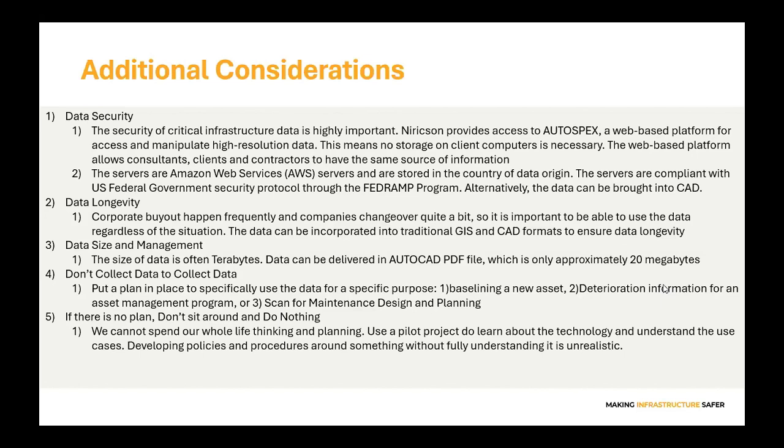The good news about this data set is that because it's all in 2D, these files can also be brought into the CAD environment. For example, we're working on several projects right now where the client needs to go out to tender for a major rehabilitation. What we're doing is helping clients move their data, these 2D defect maps, which are just basic TIFF files, into the DWG model space in the CAD environment.